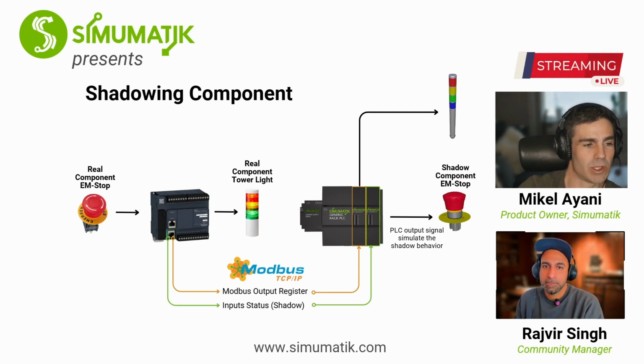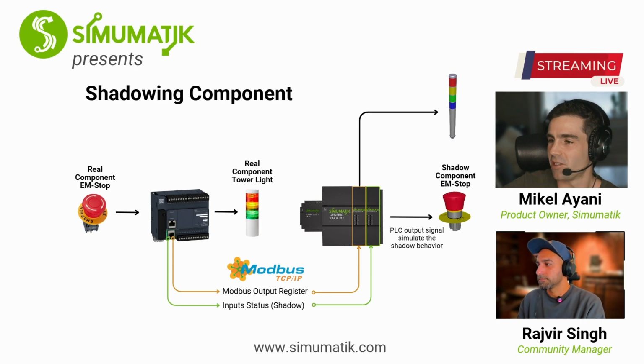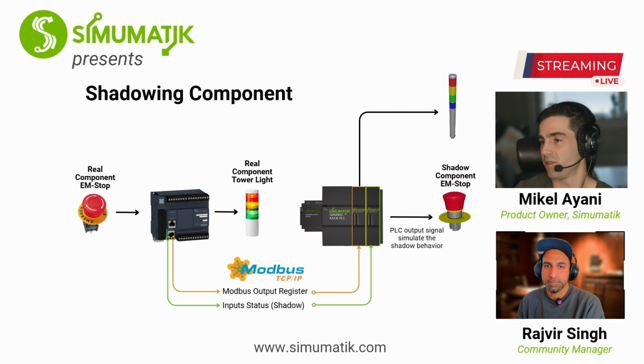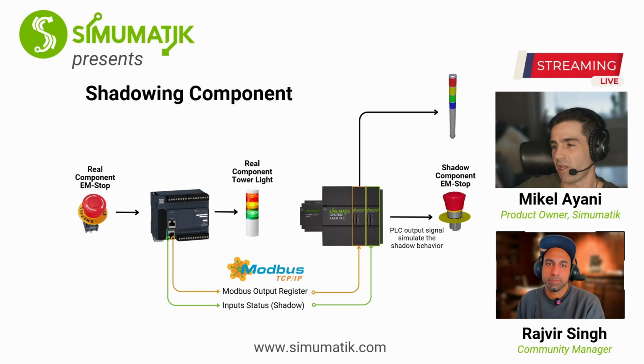So maybe what you can do is start the model modifications, if you already have an emulation model, by replacing all the input cards with output cards. So you read those signals instead, and then you need to see which components you need to modify, probably mostly the ones connected to those input cards, the sensors and so on. You need to modify them to behave like shadows instead. So you don't need to build the shadow model from scratch if you already have an emulation model, but you need to do some modifications as you are explaining.